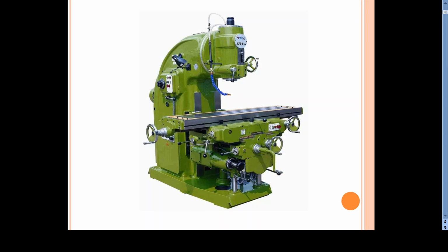It's a versatile machine common to all machine shops, and compared to shaper and planer, this is very useful, and accuracy, metal removal rate, etc. are very high compared to shaper machine. And as it uses a multi-point cutting tool, the operation will be very fast, less energy is required, and whatever the shapes which can be obtained in shaper, we can generate here also.